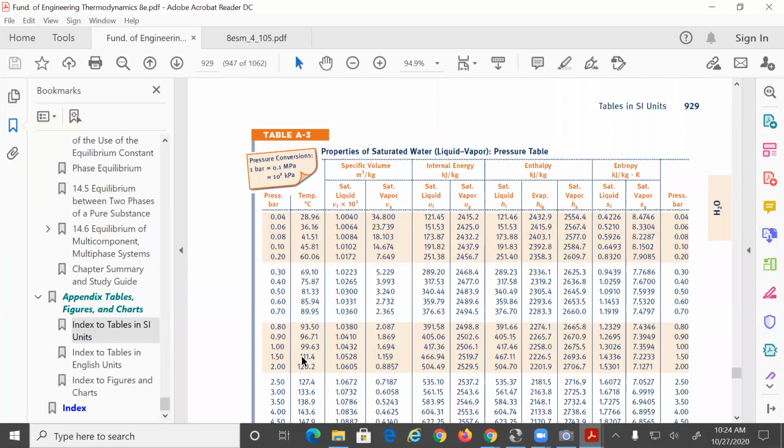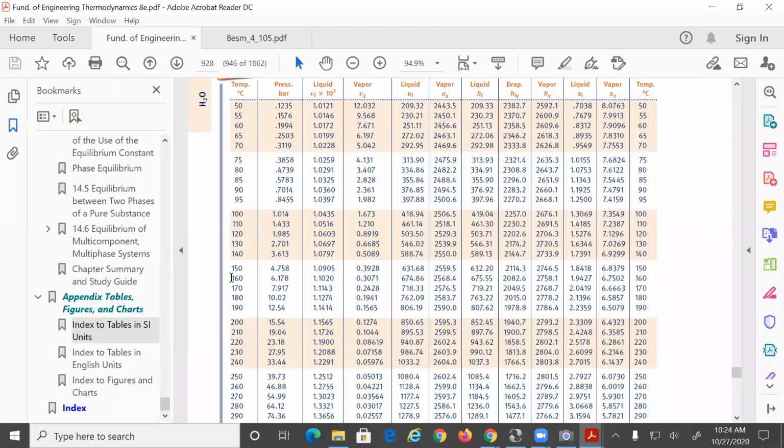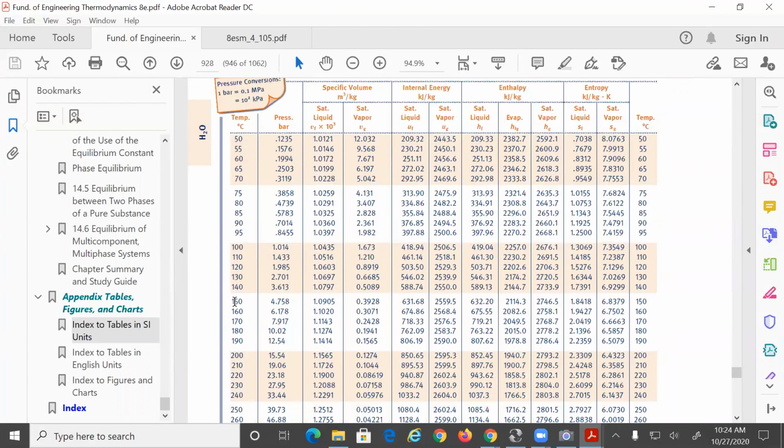What you need to do is go to the table of the temperatures and see what would be from table A2, the H at 180. Okay, so at 180, what would be the H? H fluid is what? 700 and, I'm on the red line, 763.22.